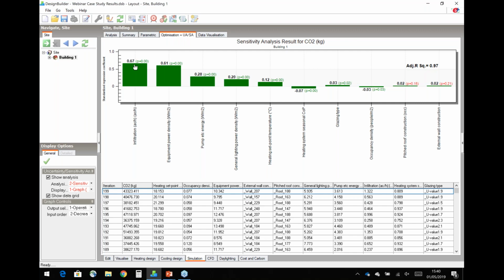For this analysis, the most important factors are related to systems and uncertainty in operations and loads. Being a naturally ventilated building, air tightness is a big issue and can contribute towards lower performance. This is because, due to operable windows in naturally ventilated buildings, sealing around the openings requires significant care and attention.